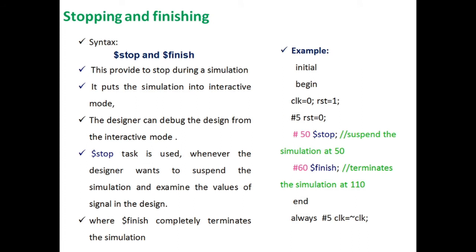stopping and finishing. So what are stopping and finishing? They are $stop and $finish. The task $stop is provided in our Verilog HDL to stop the action during a simulation. That means execution is stopped for some time. The $stop task makes the simulation go into an interactive mode such that the designer, for example the one who is developing the design, can debug the design from the interactive mode.